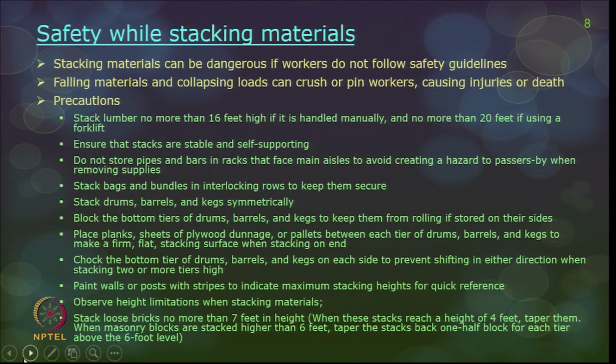Some of the precautions I have picked out. There are too many precautions for all of the materials available in the IS code and in the OSHA subparts. You can go through them later. Stack lumber no more than 16 feet high if it is handled manually, and not more than 20 feet if it is handled using a forklift. Ensure the stacks are stable and self-supporting.